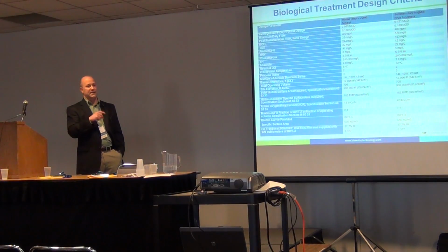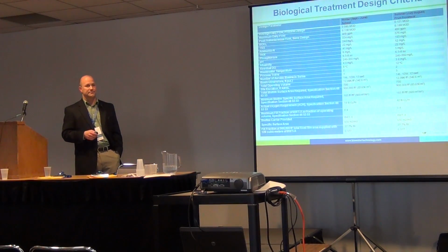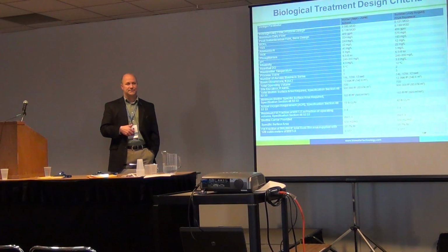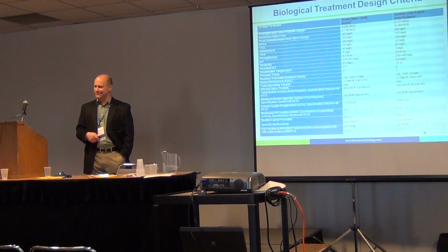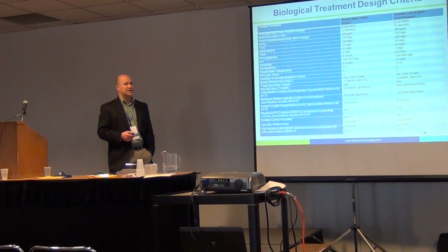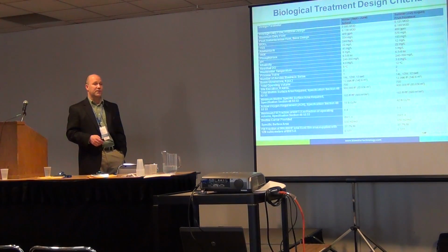All the data in this data set was taken out of the secondary clarifier. They actually retained the right to use those lagoons as post-equalization, post-holding, and discharge, so they can discharge seasonally. But in the design, they weren't expecting any additional treatment. That was my next question. What happened with the old lagoons? They left them in place and online as post-equalization and holding. Usually in Minnesota it's 180 days? 180 days. I'm not sure what Michigan is, but I'm assuming it's around there as well.